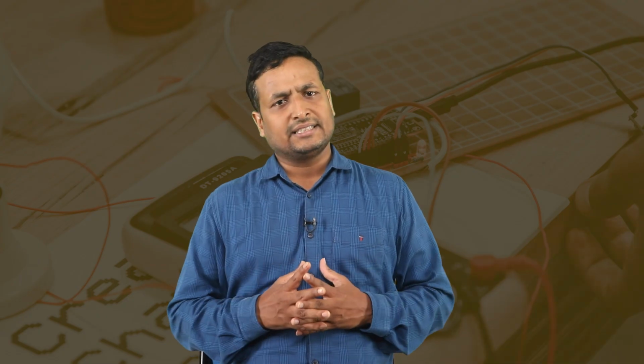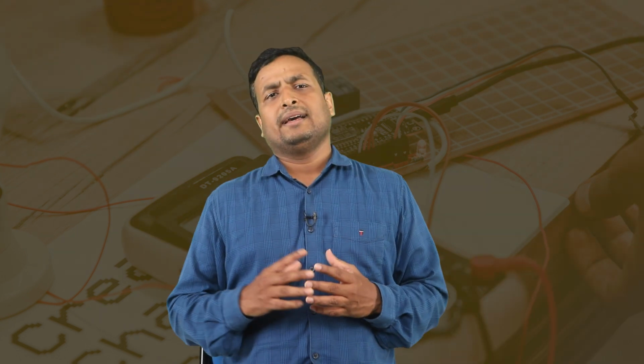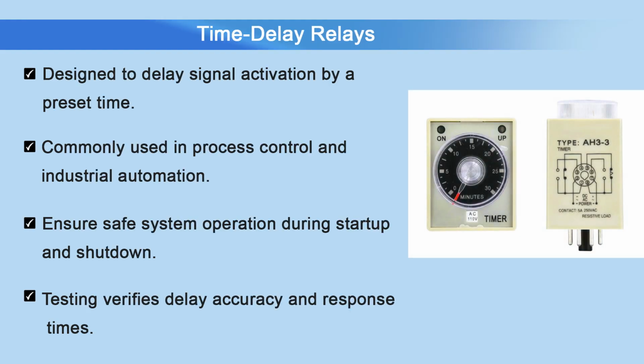So, what are the testing considerations here? These relays require testing for contact resistance, timing and magnetic sensitivity. Ensuring the relay operates correctly in response to specific magnetic field strength is very crucial in such types of conditions. Next, we will see the time delay relays.